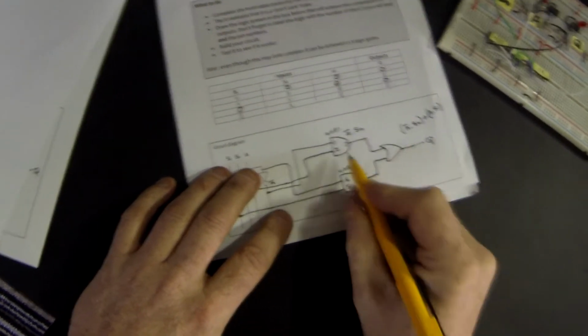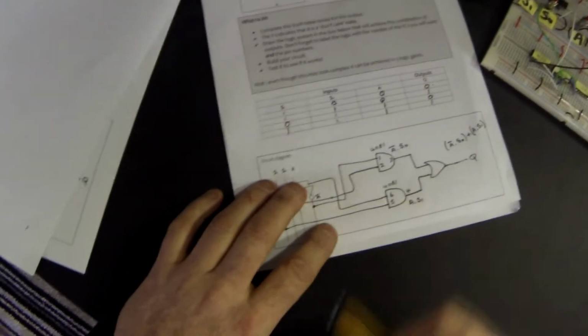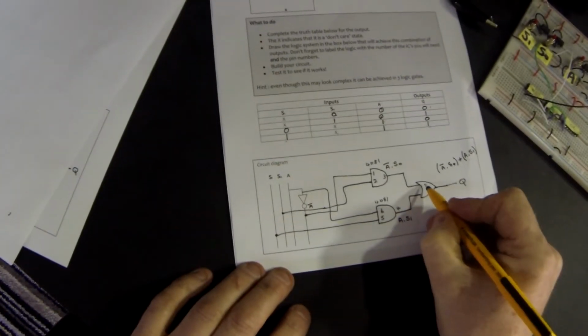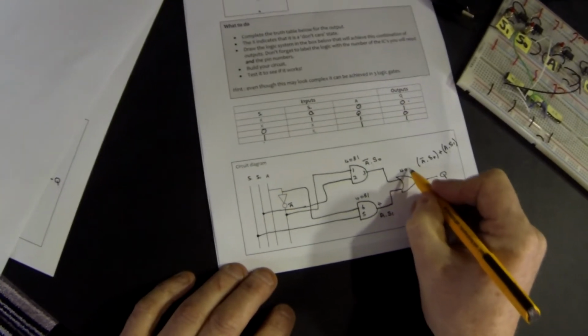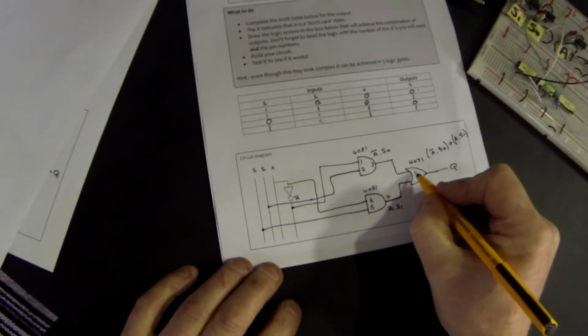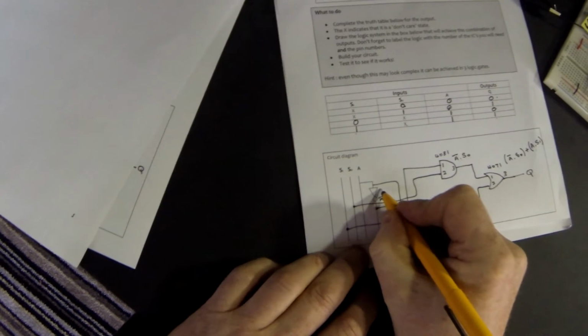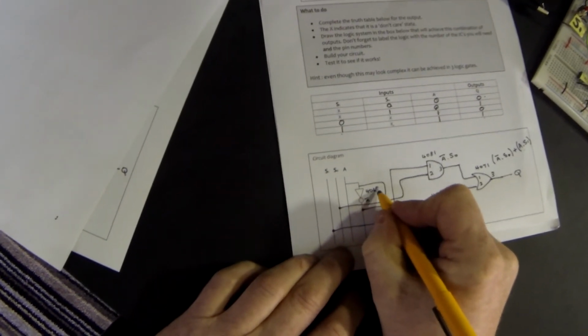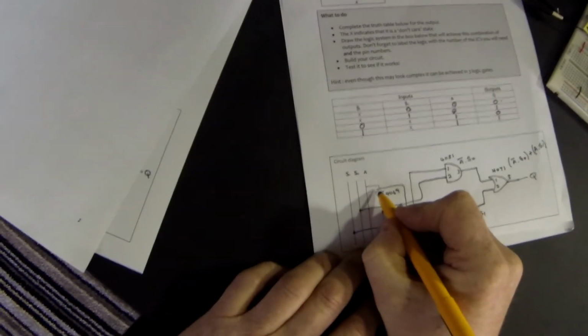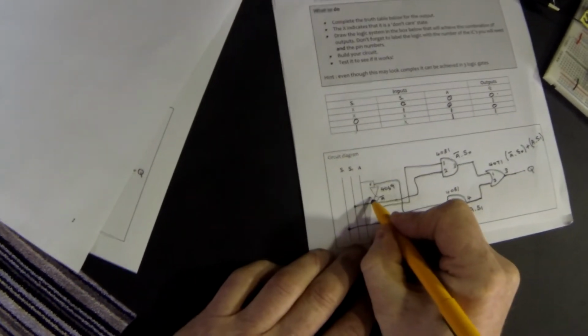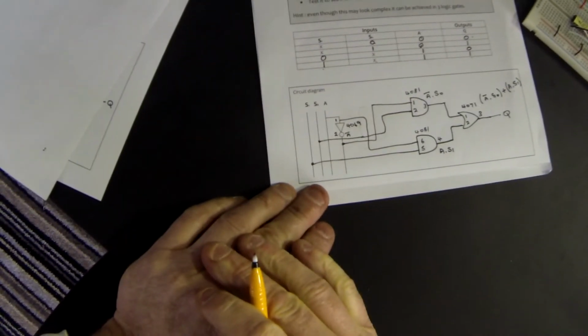Notice they don't go sequentially like these. If you look on your data sheet, you will see that that's what happens. The two inputs are 5 and 6, the output is 4. In our OR gate, which is a 4071, we're going to be using pins 1, 2 and 3. And over here on our 4069 NOT gate, we're going to be using the input pin, pin 1, and the output pin, pin 2.